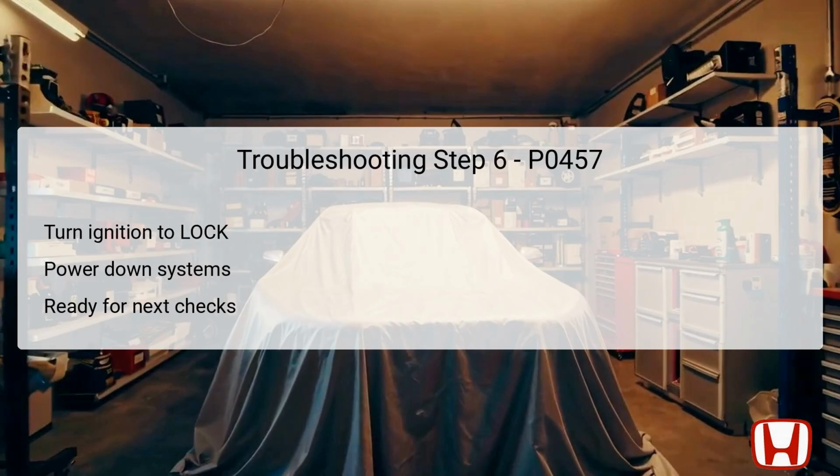Properly locking the ignition switch acts as an important procedural step, securing the vehicle and safeguarding both the technician and the equipment being inspected. Once the ignition is securely locked, you will be ready to proceed with the next part of the troubleshooting process. Step 7 involves the removal of the EVAP canister vent shut valve from the EVAP canister. This valve is essential for